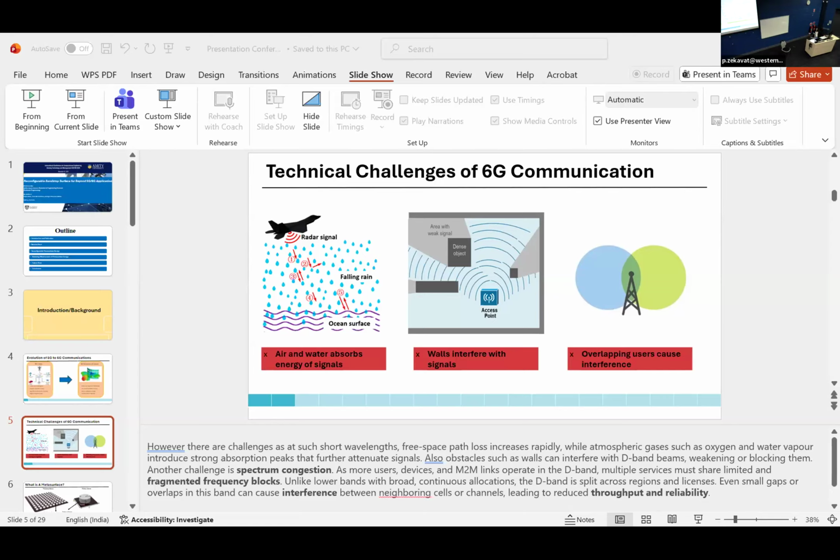So next, these results here show the transverse electric mode, normal mode, starting when all the diodes were off. You can see a clear stop band at 110 gigahertz. And then when the bottom diodes are on, it shifted to 109 gigahertz. And then when the top diode is on, the main stop band moves upwards to 116 gigahertz. And then when all the diodes are on, it shifts to 114 gigahertz.